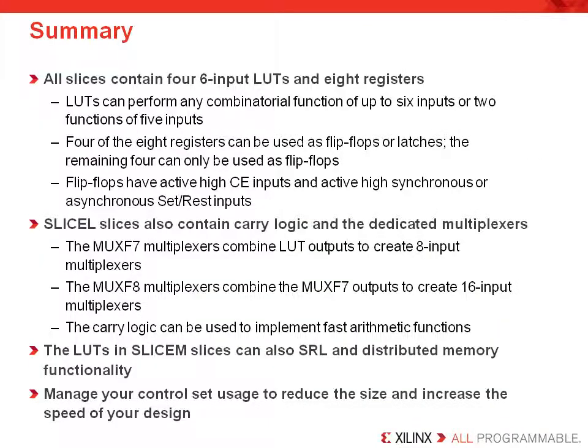In summary, all slices contain 4 6-input LUTs and 8 registers. LUTs can perform any combinatorial function of up to 6 inputs or 2 functions of 5 inputs. 4 of the 8 registers can be used as flip-flops or latches. The remaining 4 can only be used as flip-flops. Flip-flops have active high clock-enable inputs and active high synchronous or asynchronous set/reset inputs.